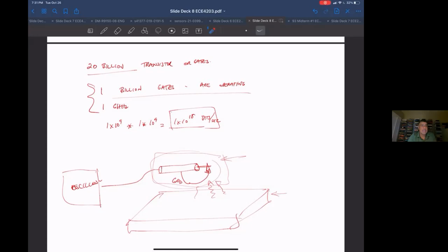And where it happens is when the system's built and you're debugging and you're going, why? This memory was working before, now when I put it on a separate board with a connector, it's not working anymore. Why is that? Or it worked at a certain clock rate, but even though it's specified at this clock rate, it's still not working. Or I made this cable and when I plug the cable in, it doesn't work. So a lot of that, you'll come back to these concepts of noise margin and correcting for noise margin, et cetera. And I think that's when it'll kick in.